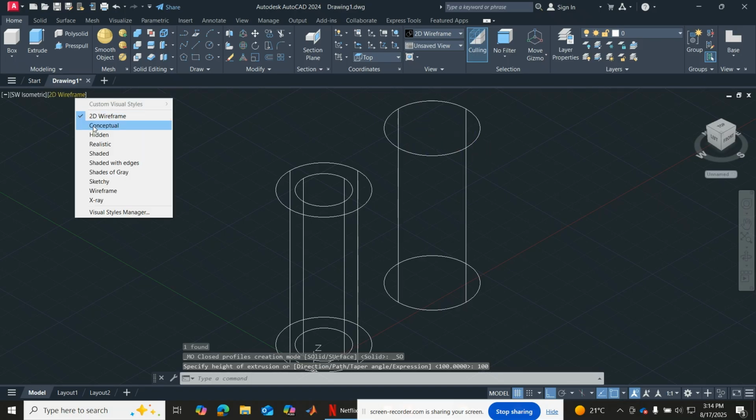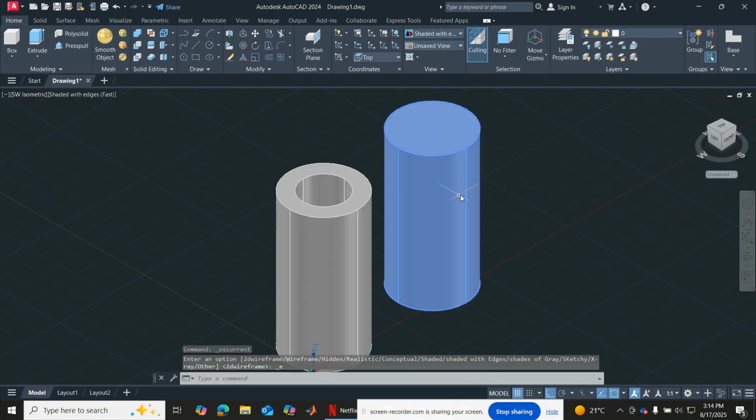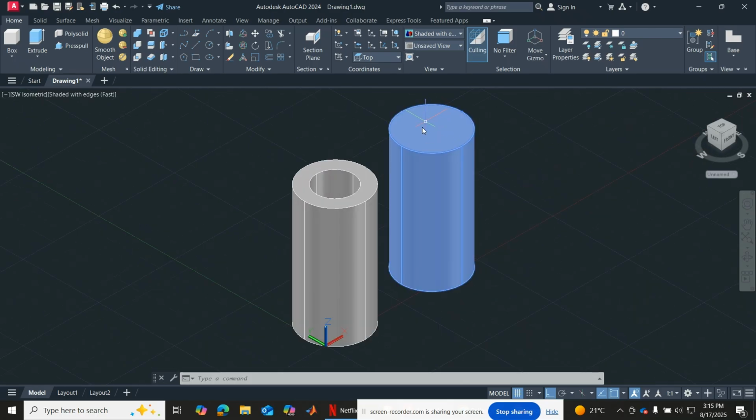So you see, I have a solid object here that I want to create a hole in between, a hole of 30 diameter, right? So what I'll do, I'll draw another circle on top of this and I will extrude it downward, even if it goes beyond, even if it reaches exactly this level or I go past it. And then that item I draw now I will subtract. When I subtract, I will remain with the hole. That's where the subtraction command comes, right?